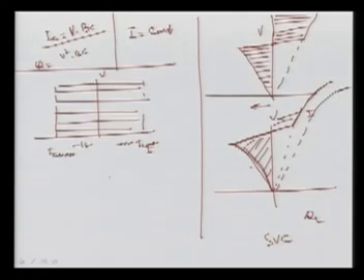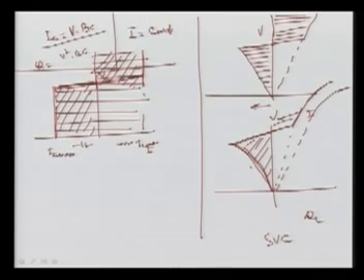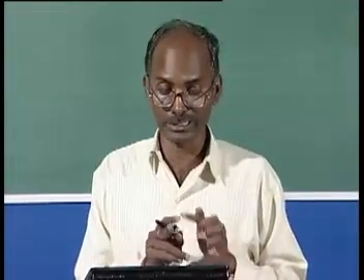So the actual characteristic is normally operating in this zone when the voltage is less, and when the voltage is higher, it will be operating in this zone. So this hashed line area is your operating zone. Here again we have to provide the slope. So now you can say it has the wider range, as I said in the very beginning when I was comparing the SVC and STATCOM in the previous lecture.